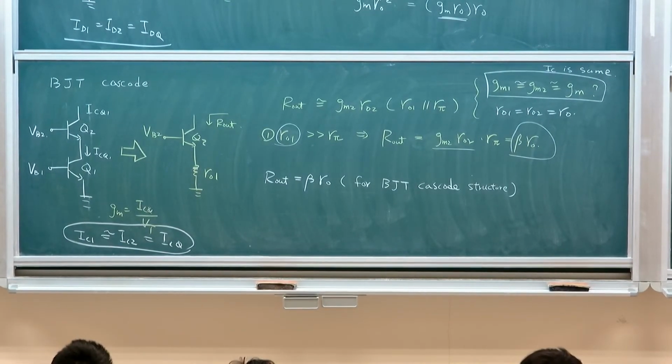So that will lead to a limitation as to how one stacks things up. So let me explain why. If you talk about MOSFET and the difference between a MOSFET cascode current source and that of a BJT, one of the things is that if I'm not satisfied with this output resistance, what can I do next? I'm stacking 2.